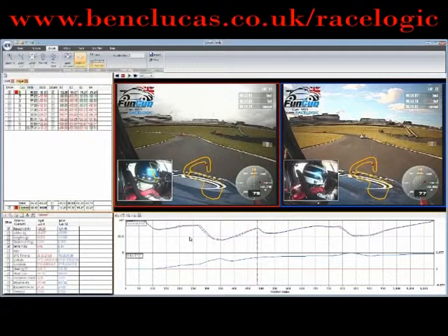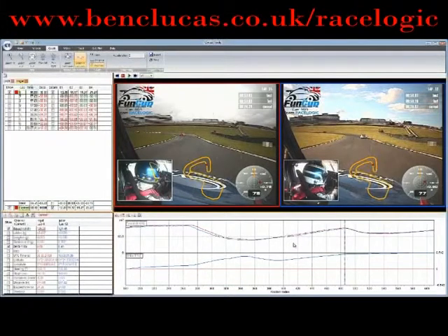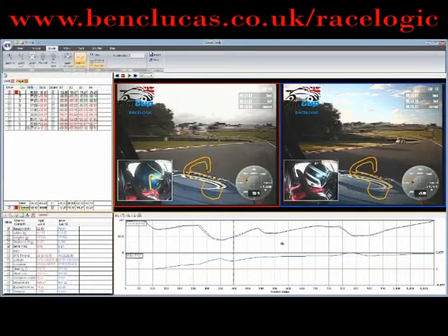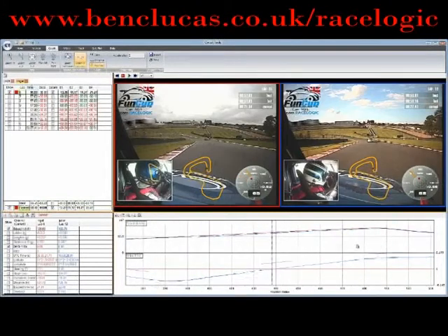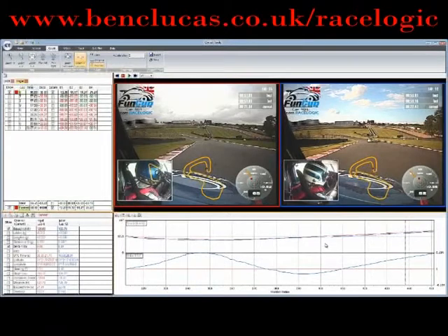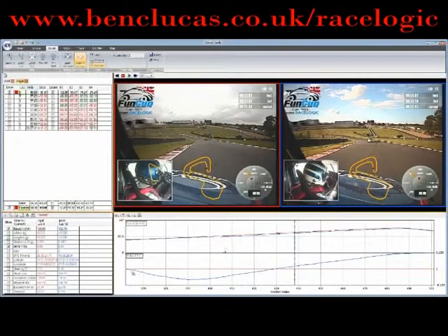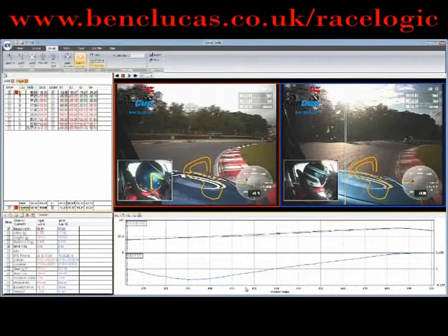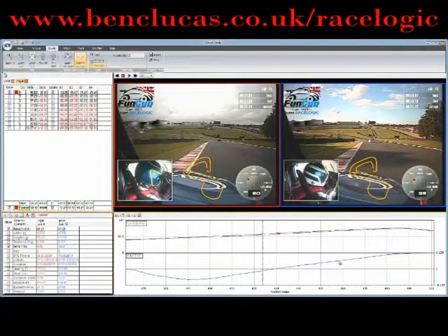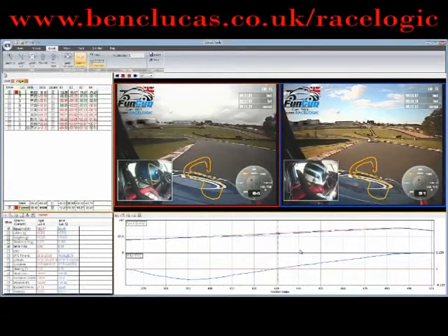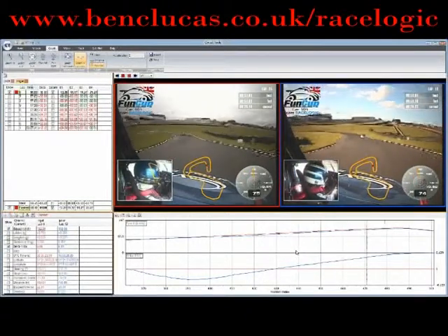You can zoom into the graph by clicking and dragging the cursor from the left to the right using the mouse. You can zoom out by clicking and dragging from the right to the left. You can pan by right-clicking and dragging with the mouse. When you zoom, the delta T starts again from 0 to make it easier to analyse the specific area of interest. You can play back the video at any time by pressing the spacebar to start and stop, and the backspace key to return to the previous starting point.